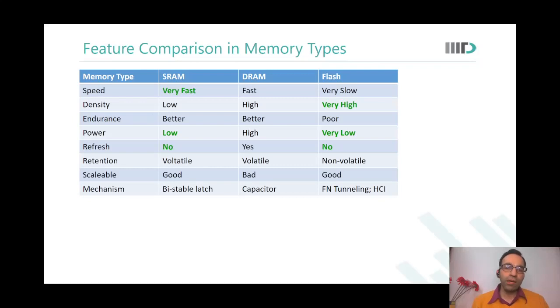If you take the course on solid state devices and study the reliability mechanisms there, you will see that when a device is operated at a very high voltage, its reliability degrades very significantly. So you can use the device at a very high voltage only for a short duration of time. As we will see later in the course, when we design flashes and do read and write in the flashes, we operate the memory at very high voltages, 12 volts, 15 volts, 18 volts. So the device degradation is very fast, and therefore flashes have low endurance.